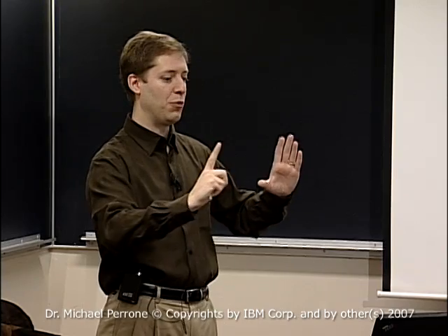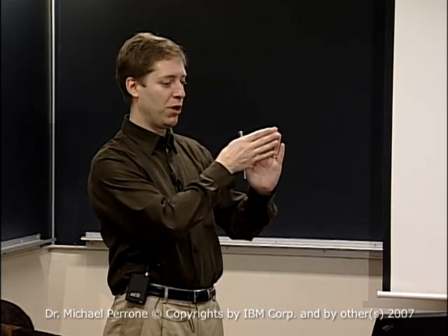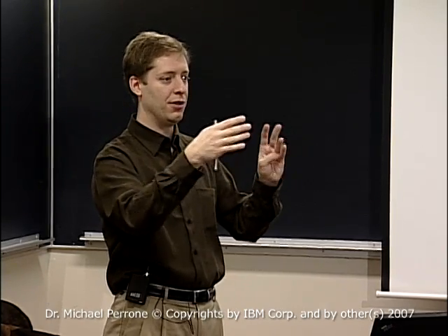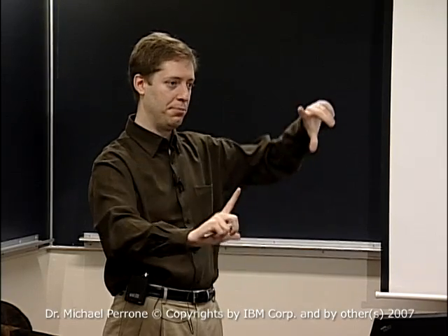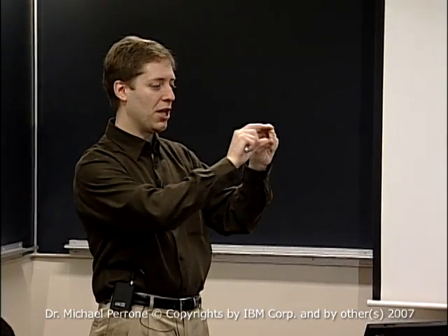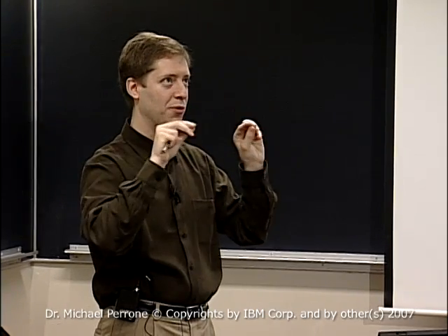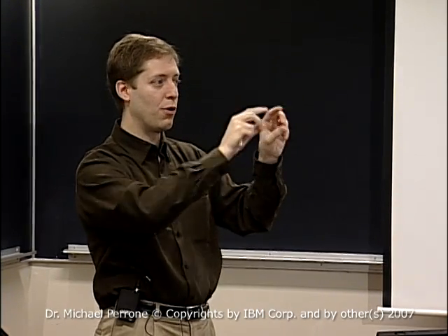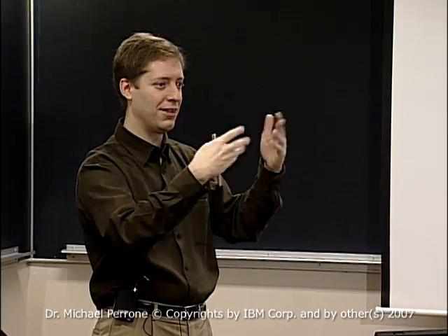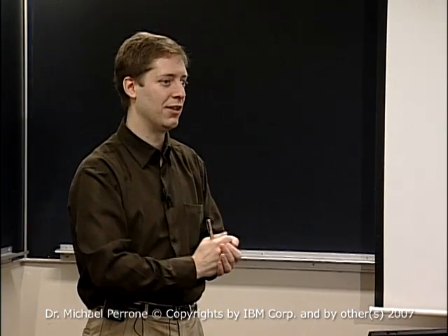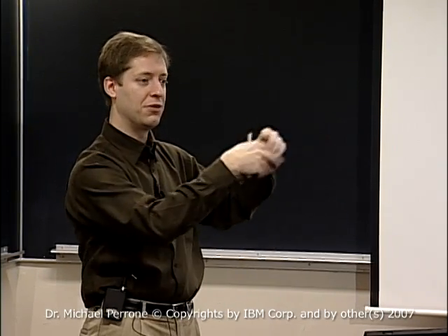Typically the FFTs that we work with are somewhere from 1024 to 2048 square. And so it's possible to take, say, the top 4 rows. In the case of 1024, 4 rows, complex, single precision, I think it's 16 kilobytes. And so that fits into local store very nicely. So you can start multi-buffering.